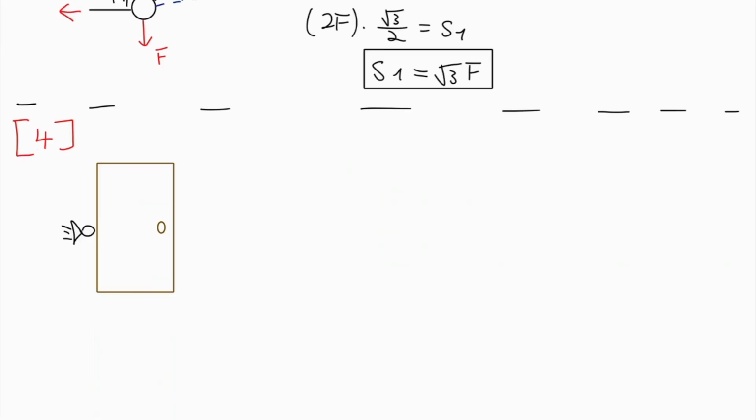For moments, the summation is a little bit different. So moments describe a rotational force. The moment is always equal to a force multiplied by its perpendicular distance to your reference point, okay? This distance is often referred to as the lever arm. So the moment the force generates is very heavily dependent on what your reference point is because of the lever arm's distance being able to change, okay?